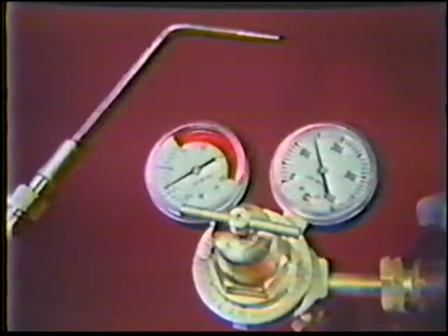The gas pressure and the tip size combine to control the flow rate and therefore the amount of heat. A neutral flame from a proper orifice size, but with too strong a gas pressure, will form a deep puddle and probably burn holes in thin gauge metals. The same flame with correct gas pressure, but with too large a tip size, may add too much heat to the metal. In both cases, the temperature of the flame remains the same. Only the amount of heat changes.